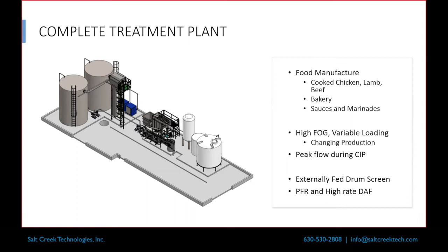Again, the solids loading was actually not super high, so we were able to do high rate DAF, and then we were also able to do a PFR system because we installed enough EQ tank up front that the flow through the DAF was fairly balanced. So the PFR would keep it a fairly constant flow rate. And that's the pipe flow reactor. Makes it a chemical treatment system.